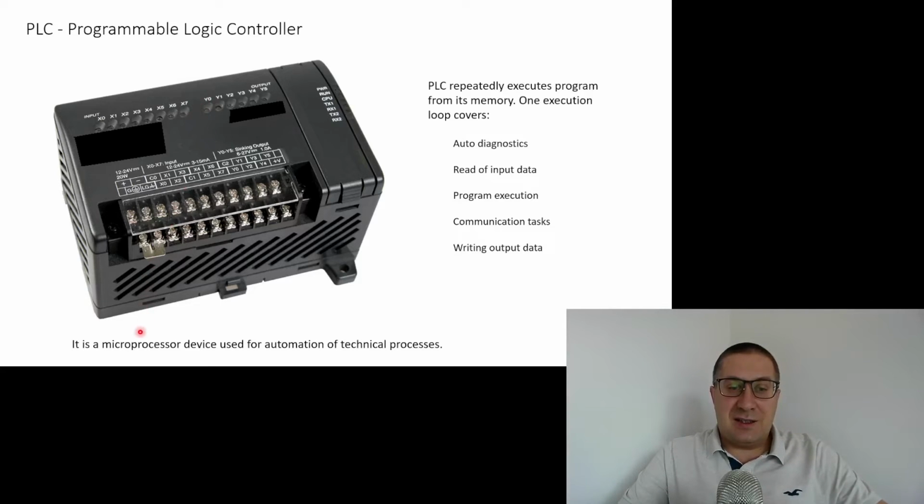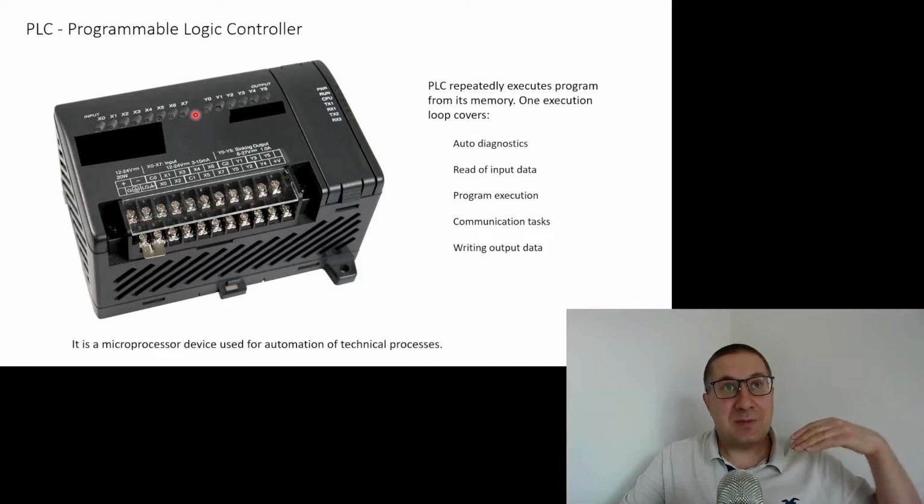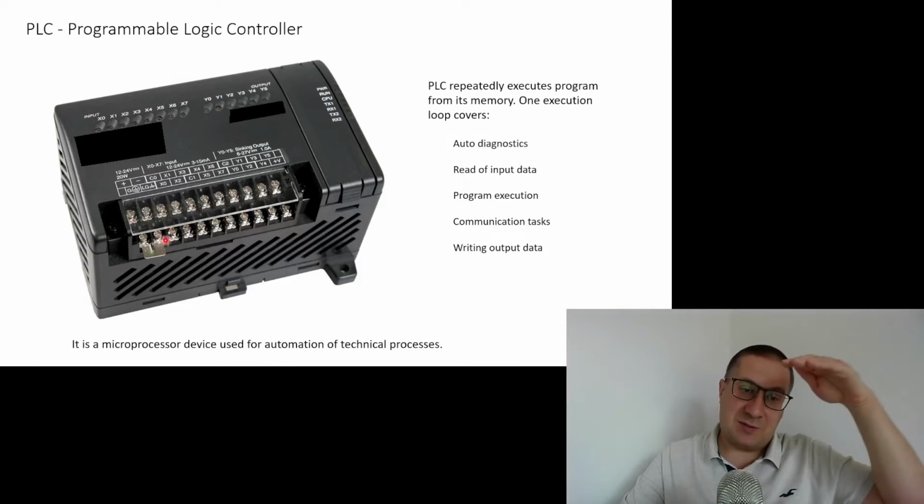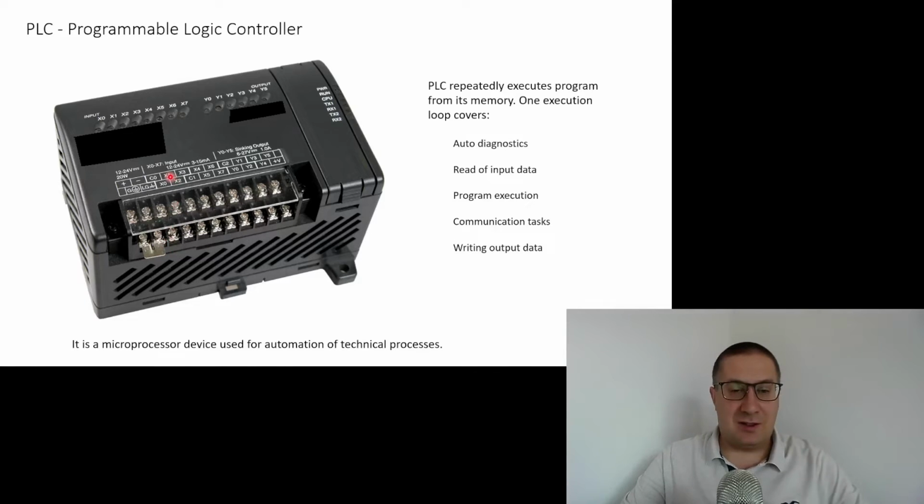and if it's the sensor that checks if the level of the liquid has been reached in a tank, we can say that, for example, the algorithm will check when the value of x1, if we connect the cable from the sensor to x1, has a value of 1. If it has a value of 1, it will, I don't know, stop the pump, right?